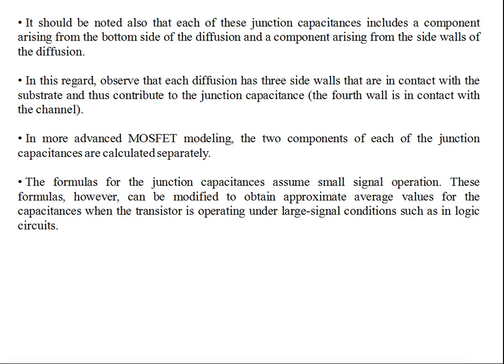It should also be noted that each of these junction capacitances includes a component arising from the bottom side of the diffusion and a component arising from the side wall of the diffusion.